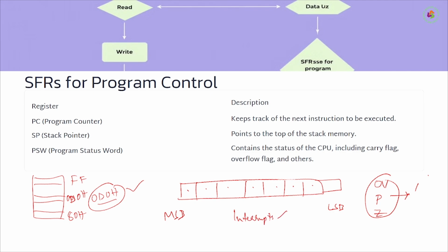For interrupts, particularly timer, there are flags that show the condition of the situation, where by instruction execution we can check whether the timer has overflowed or not. If it overflows, an interrupt will be given. Parity is used in serial communication, where you can check even parity and odd parity for error detection and error correction. You can also check whether the operation resulted in 0. If the result is 0, the 0 flag will be set, and in this manner flags work.